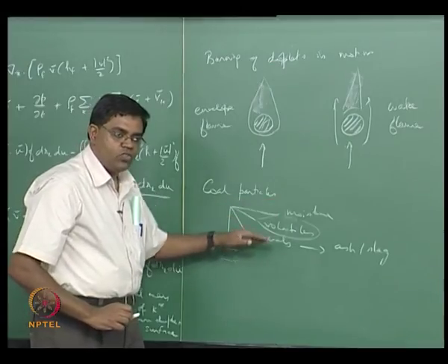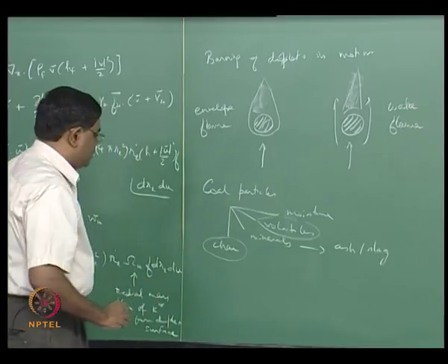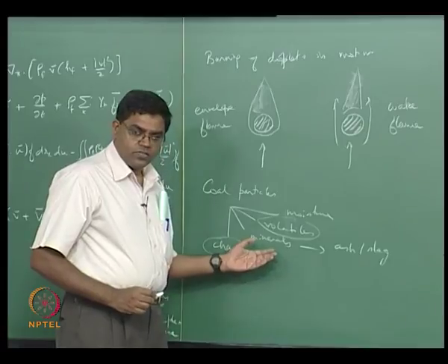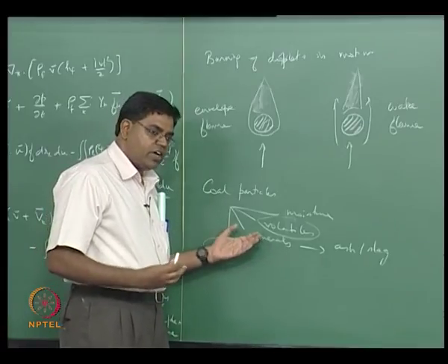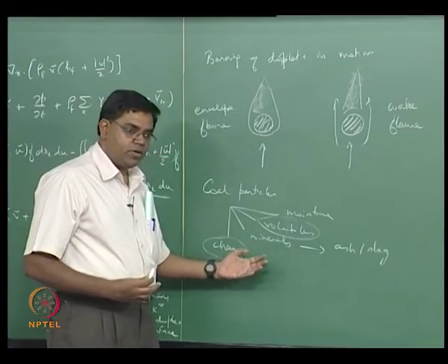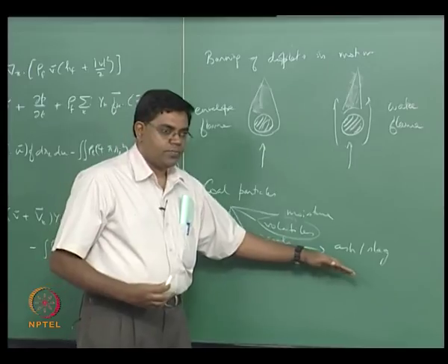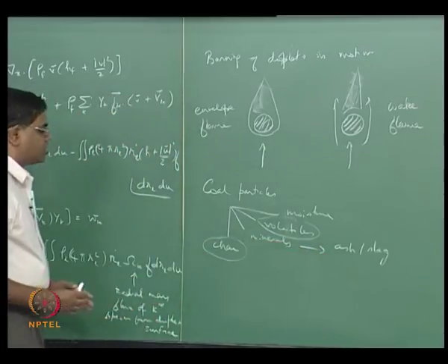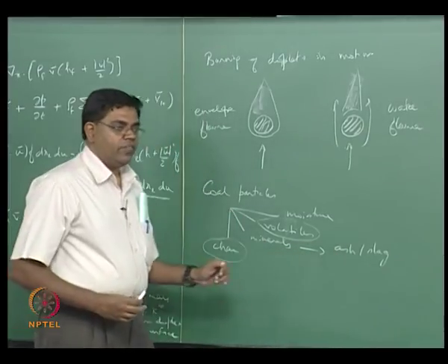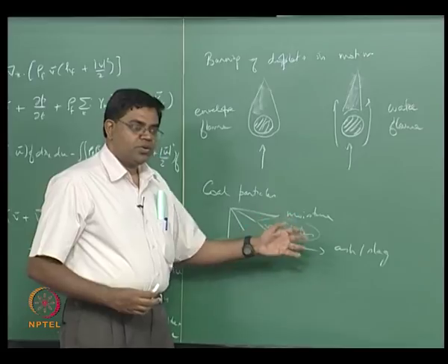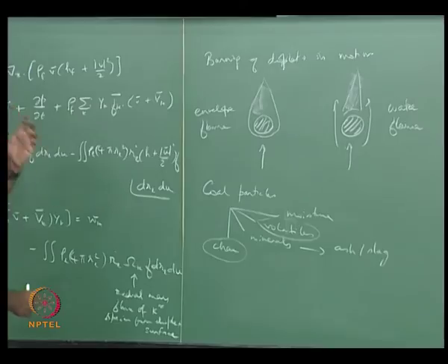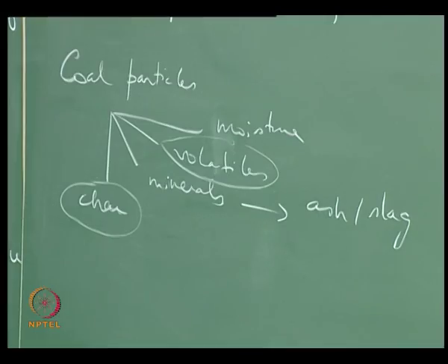The other ones could actually soak up energy, alright, and this is pretty important because in the case of Indian coals, and India really relies a lot on coal, and there are a lot of coal reserves here for quite some time that we can burn, but it is all very high ash content, okay. So the ash content could be as high as somewhere like 30 to 40%. It's almost like we have coal and ash rather than ash and coal, okay. So that's the kind of situation we have as far as coal is concerned.